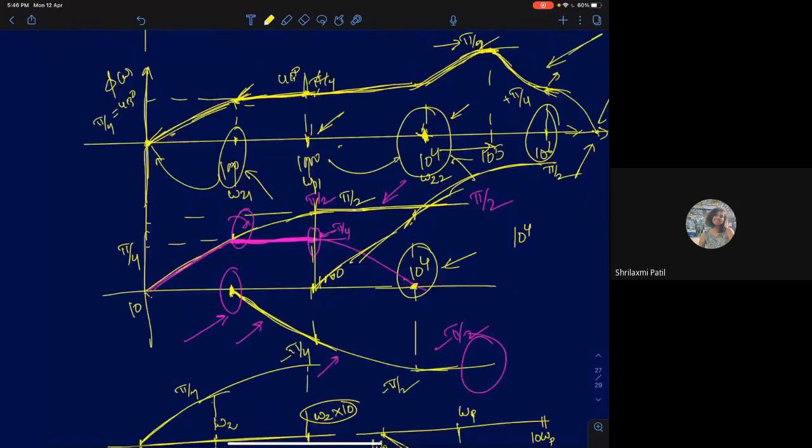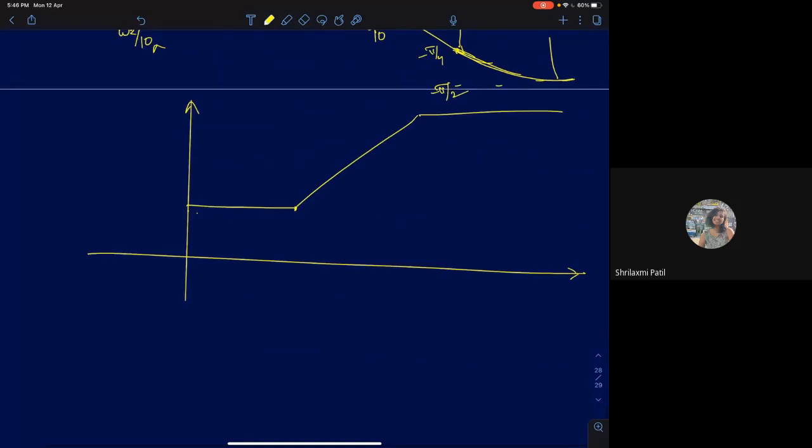Okay? So finally, I've given you a transfer function which looks like this. Now from this, can you tell me what is the location of the pole and 0? I'm giving you the DC gain is, let's assume, 0 decibels. I'm giving you this is 100 and this is say 10 power 4. 10 power 4 is 2 decades away, so this is 40 decibels.